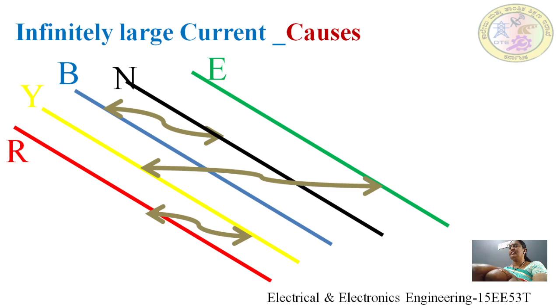These are all the conditions which are caused when there are wooden or tree branches falling on the transmission line, or there is a bird which touches the transmission line. Here all the categories are there, that is phase to phase fault, phase to neutral fault, phase to earth fault. All the types of faults are present in this case, which leads to infinitely large current.